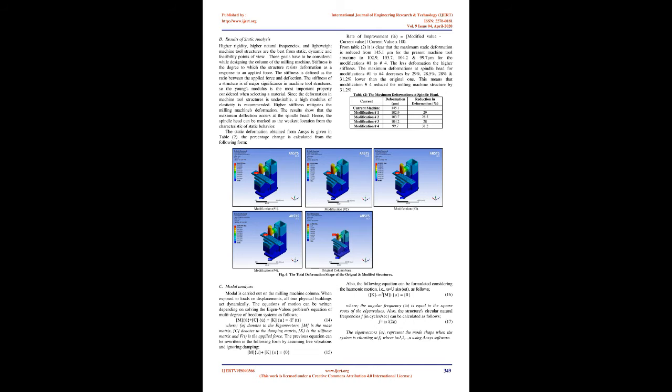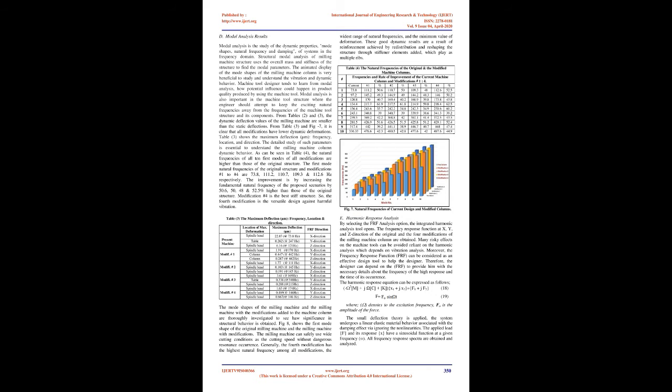Static analysis. Static, modal, and frequency analyses were done by using Ansys software. The evaluation of the static load's effect on structure deformation X can be evaluated as follows: Qx equals F (12), where F denotes the static force applied to the spindle nose, which equals 4000 N as an assumed value, and Q is a constant.